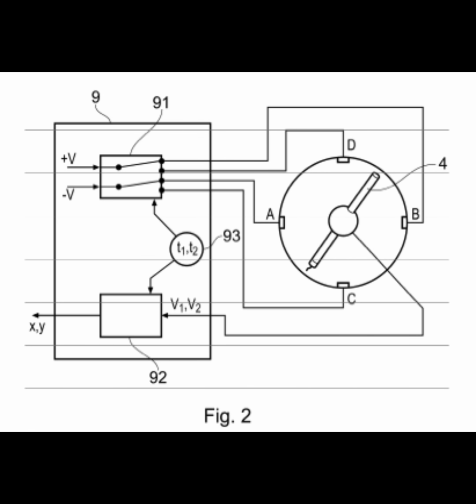In practice, the actuator is usually being moved by a user. In order to ensure that, even when the actuator is being moved quickly, the output signals accurately represent the actual positions of the actuator, the time periods T1 and T2 have to be very short. For example, each of the time periods T1 and T2 can be 0.01 seconds.